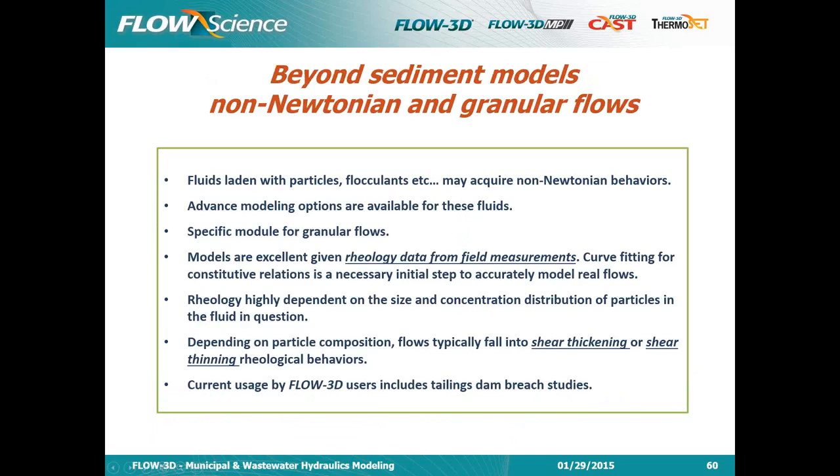Now, going a step beyond, when fluids are laden with particles and flocculants and so on, depending on the size and concentration, the fluid may acquire non-Newtonian behaviors. So we also have advanced modeling options for these types of fluids. We have a specific module for granular flows, and we have non-Newtonian flows as well. The models are excellent given that we have rheology data from field measurements. It's just too complex to try and guess based on particle composition what's going to happen. So you need rheology data from field measurements, and then once you have that, you can do some curve fitting and build proper constitutive relations for the fluid. So two general mechanisms we observe.